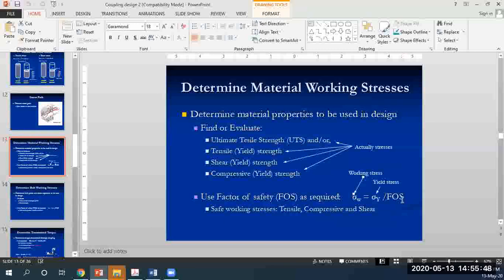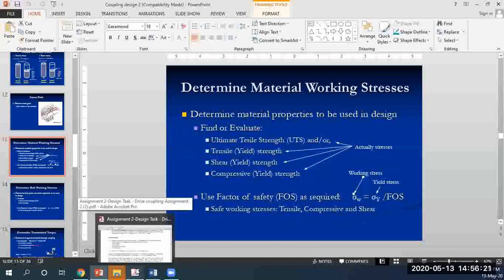So what engineers do is set a working limit which is far less than the ultimate stress limit. Why do they do that? To account for the factor of safety. So by mistake, if somebody loads up the elevator to 2000 kg, it still won't break, because the factor of safety is included in the design. So that's what factor of safety, working stress and working limits are about.